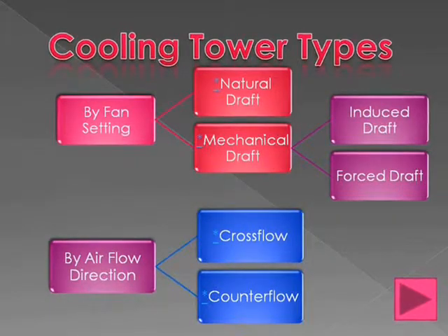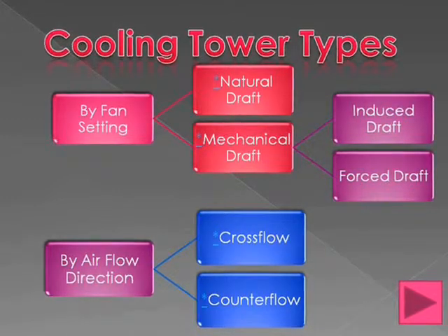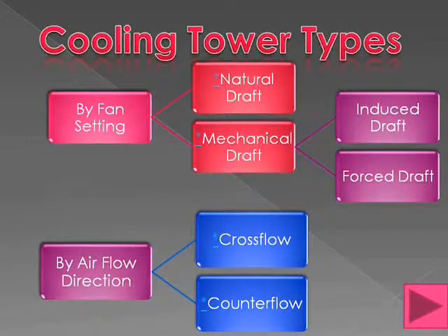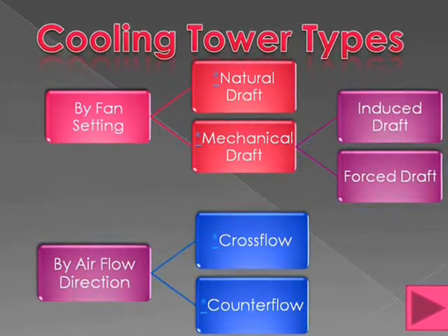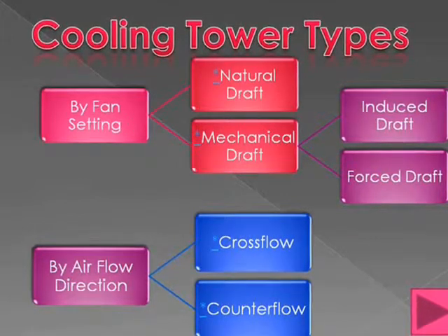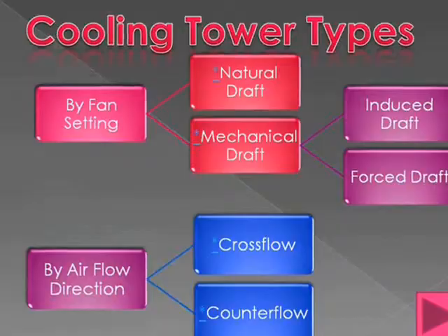Cooling tower types can be divided according to fan setting or by airflow direction. For fan setting, we have natural draft and mechanical draft, where mechanical draft can be further classified into induced draft or forced draft. For airflow direction, we have cross flow and counter flow.